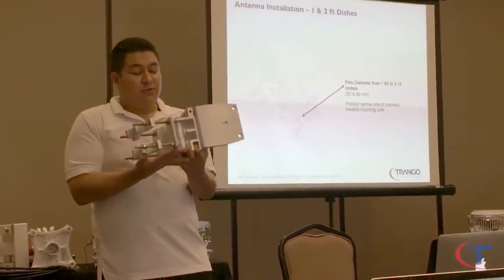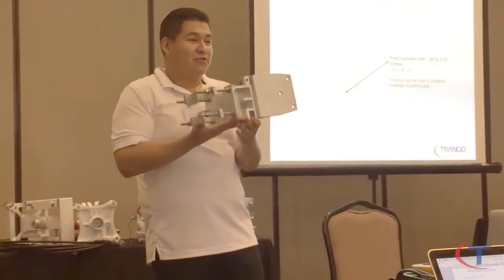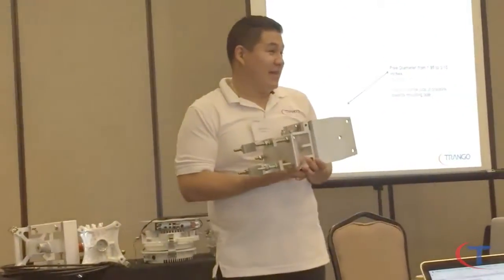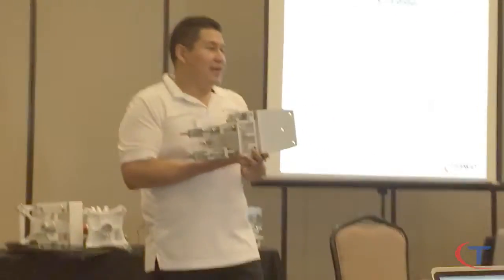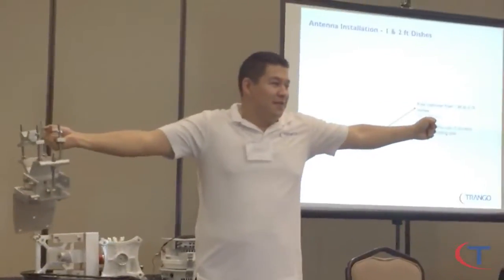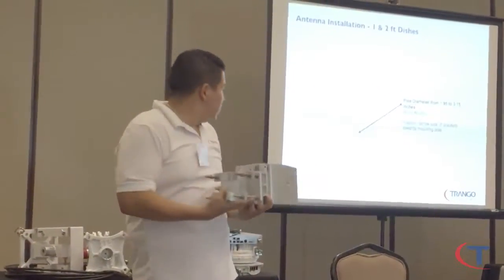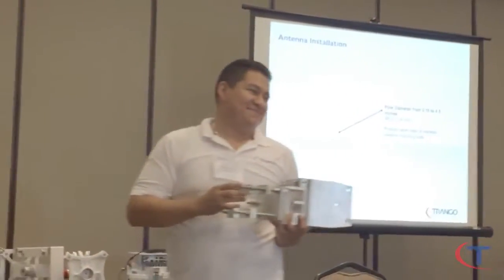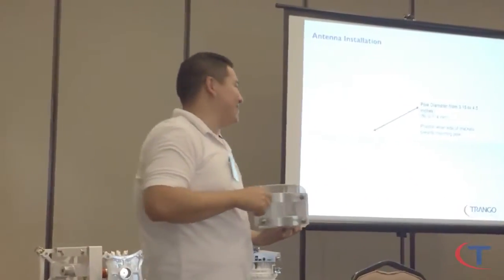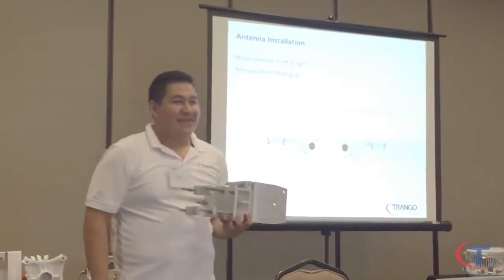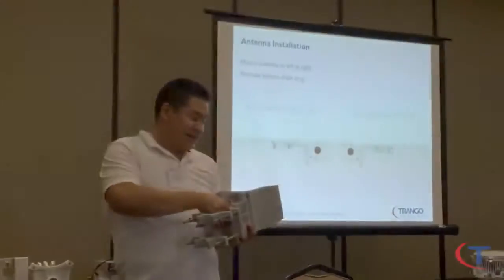Again, the mount is going to be proportional to the antenna. So a little 1 footer, 2 footer, it's not a big deal. When you go to the 6 and 12, then it's going to be a really big antenna. You're not talking about fine adjustment going like this. You're going to be talking about going like this, okay? All right. And you want a horse collar on that pipe mount. Yeah. You don't want a self-tapper. Yeah, that's going to be that. And don't take the rope off the mount that's holding it up there. Yes, until you locked it down.